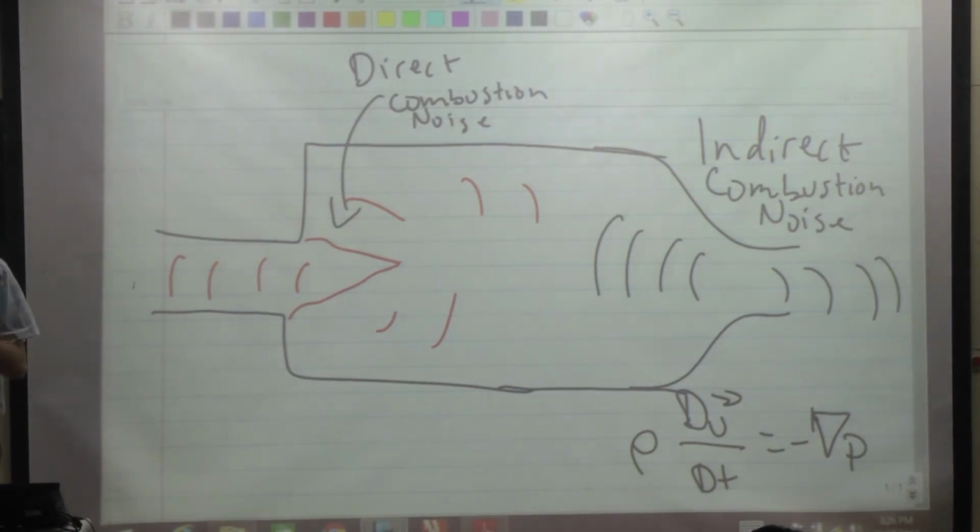Well, what gives you a time-varying force? That basically means you have a time-varying pressure gradient. And as we've talked about, pressure fluctuations are essentially synonymous with acoustic disturbances. So the entropy disturbance is the density fluctuation, which is being accelerated, which excites an oscillatory pressure gradient, which gives you acoustic waves.